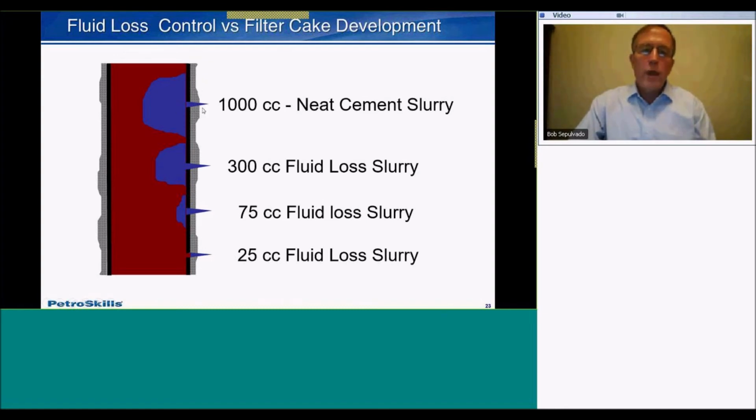So again, we're squeezing cement into a very confined area. What is happening is the water is squeezed out of the cement slurry at a very high rate in a very short period of time. And so it's building a mass behind it that is not very competent, and I'll speak more on that later. What it's doing is providing some restriction in the wellbore if you build this. So what could happen in a situation like this is you may get a false indication of a squeeze because of your restriction pressure, and you may not be able to squeeze any cement down below this interval.